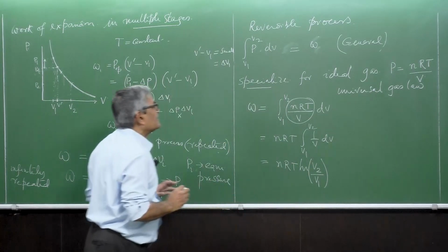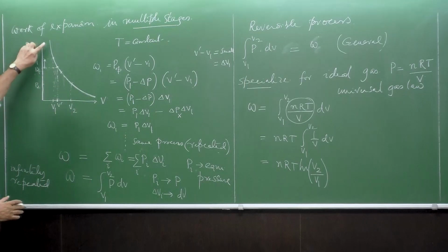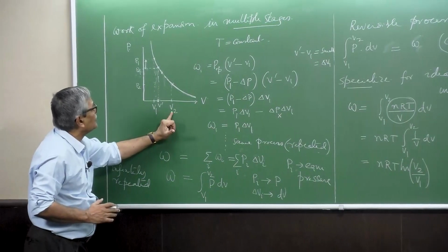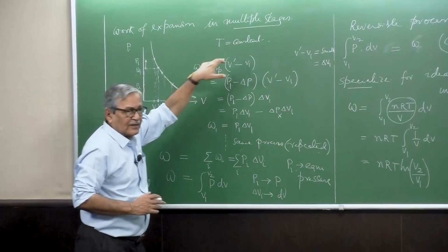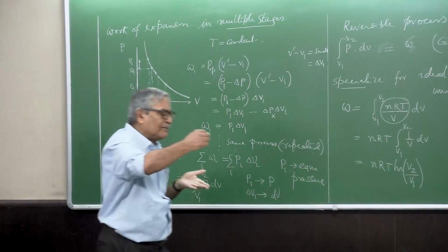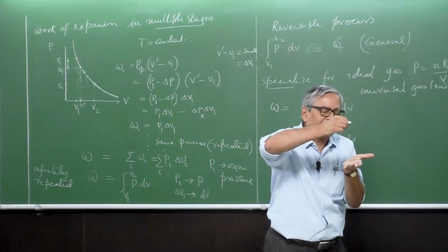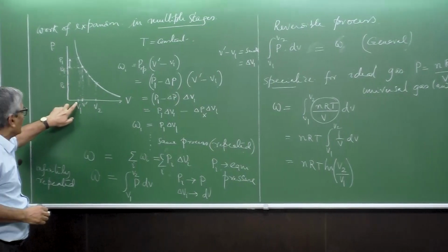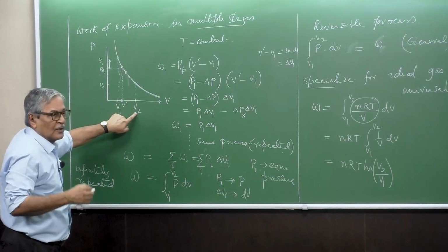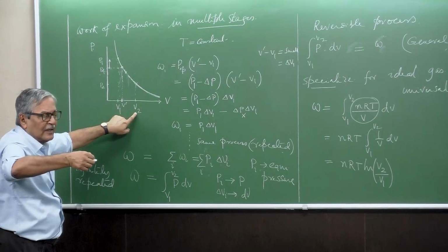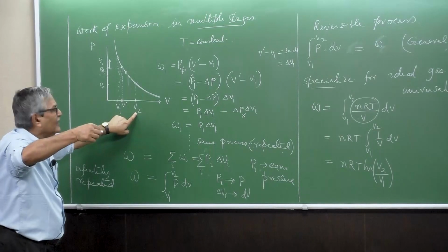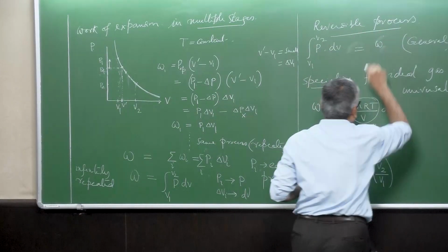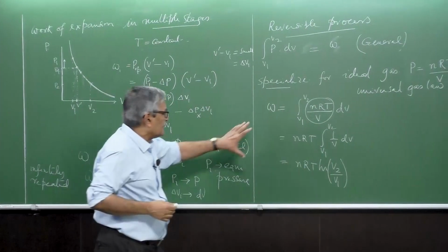So this is a very stringent condition that I have always maintained in changing the state of the gas, or the volume of the gas, from V1 to V2, keeping temperature always constant. And in the process, I have reduced the pressure of the gas by an infinitesimal amount at each stage of compressing or expanding the gas from V1 to V2. For each stage, I am lifting a weight on the piston by an infinitesimal amount, and the process is called the reversible process. So this is a reversible path, and this gives me a typical expression.